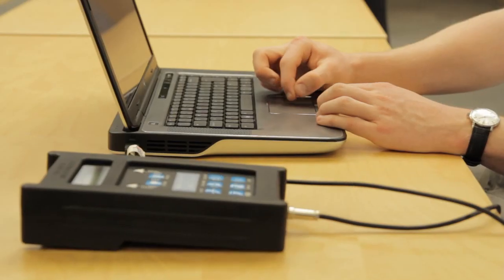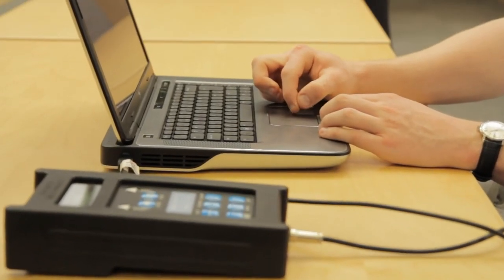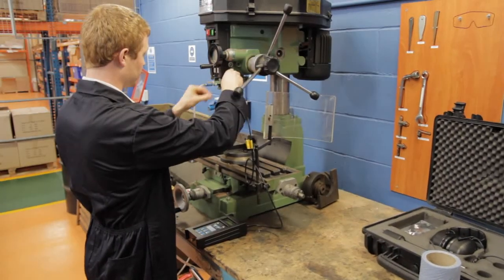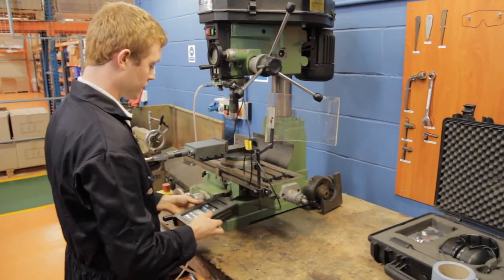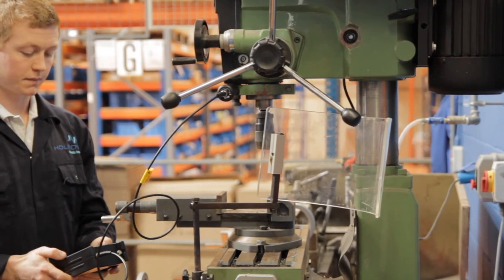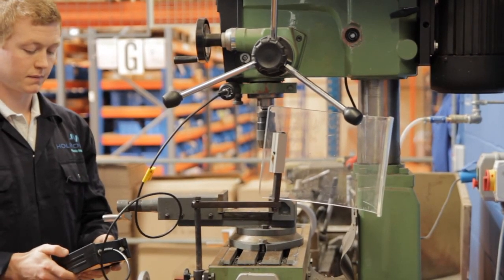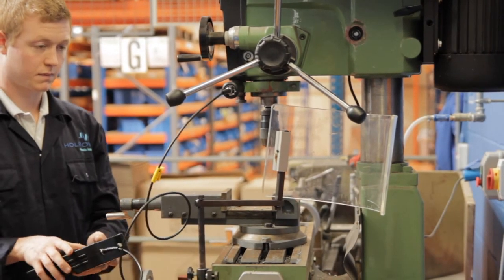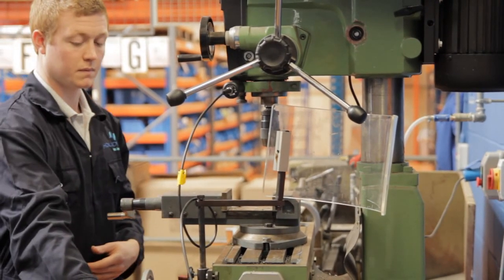Because this analysis is not required to interpret results, the speed and ease of measurement is dramatically improved compared to vibration analysis. Also, AE uses a single sensor to detect signals and does not require data collection in 3 planes as required by vibration. This de-skills the condition monitoring application to a level where complex training and understanding of fast Fourier transforms is not required.